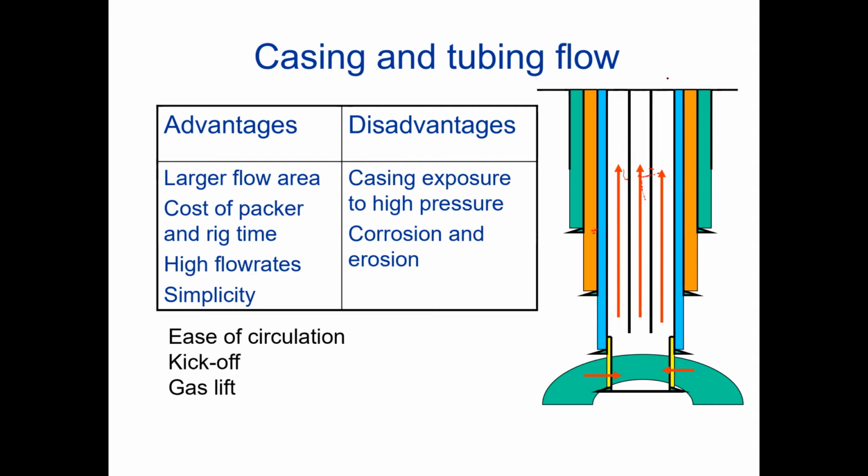They inject gas from here, it comes to the bottom, and reduces the density of the fluid here, and therefore the well can start flowing.